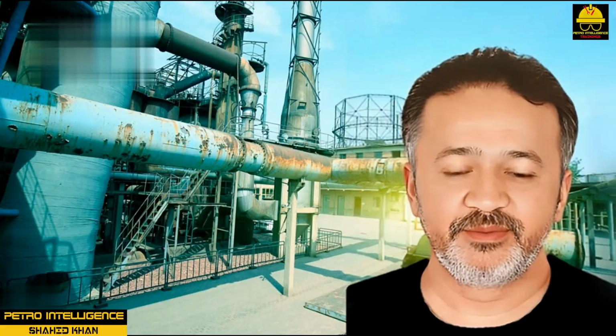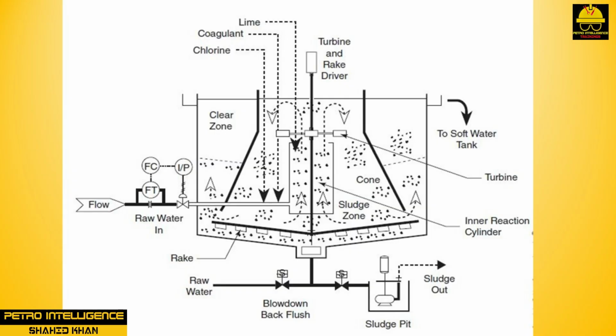Blowdown. Blowdown is a term used to describe the process in which water is removed from the boiler system. As suspended solids concentrate in the water, chemical treatment reaches a point at which it is no longer effective. Removal of a portion of the treated water is necessary.